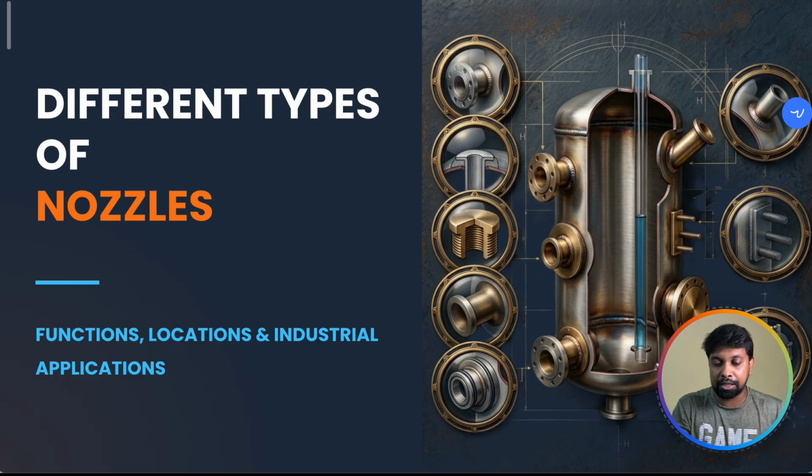Today we are going to discuss the different types of nozzles, the functions of the nozzles, where the nozzles are located, and the industrial applications of the nozzles. In this image you can see I have tried to implement almost all the nozzles. These are the nozzles connected with a flange, these are connected with the TC end, these are the blind flanges. Here you can see nozzles connected with an internal thread. Here are the manway connections. Here you can see the view glass nozzles, and here you can see the plug of the nozzle connections, and we will see everything in detail in further slides.